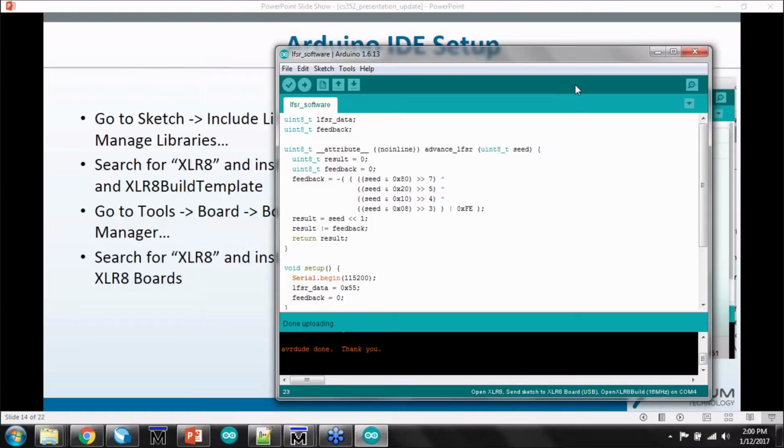And you can run it as is, and then you can start experimenting, which is making simple changes to it. Say you want to change the tap points on it, or maybe you want to add another configuration input, and slowly work your way toward making changes not only in the base RTL or the base source code for the file, but then make changes that'll impact modifications to the register interface and then give you additional features.